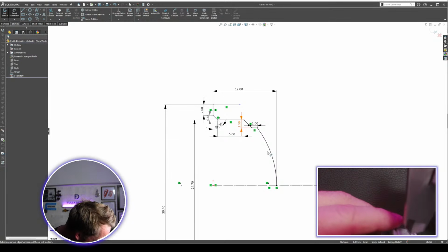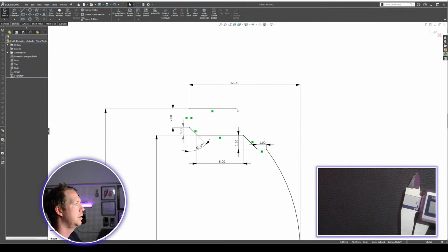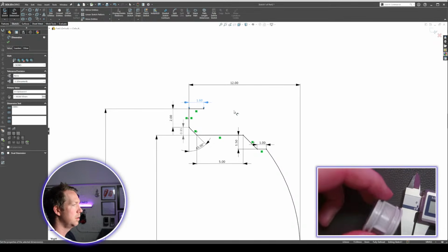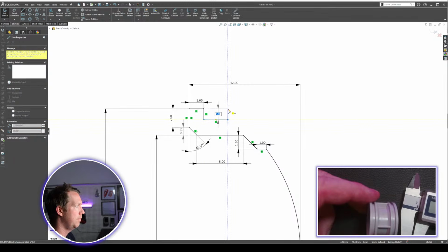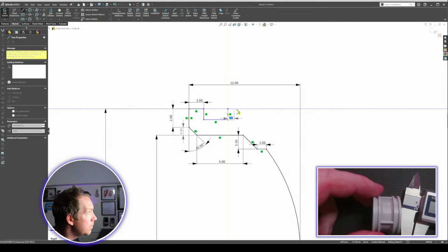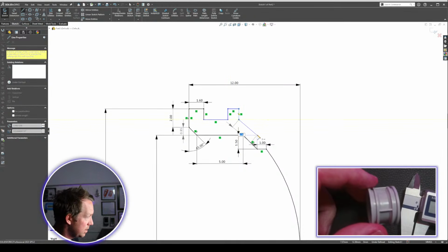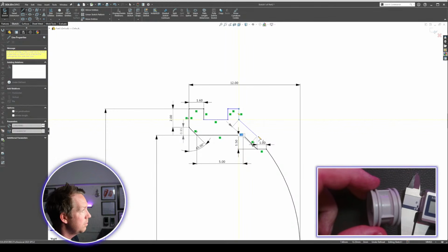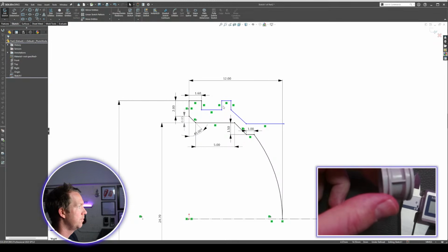So we have a flat section, which is 1.6. I'm going to put that one in, 1.6. Then there's a step down, back up, down, chamfer, which would make sense to be in line with this one. It looks like it goes pretty deep, and then step across, and that's to the middle, what looks like the middle of the wheel from the outside.